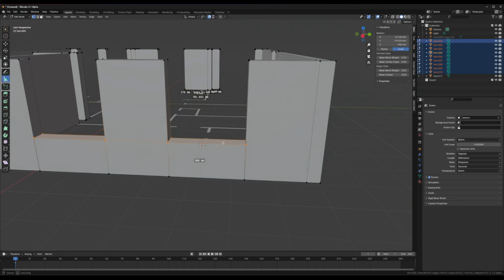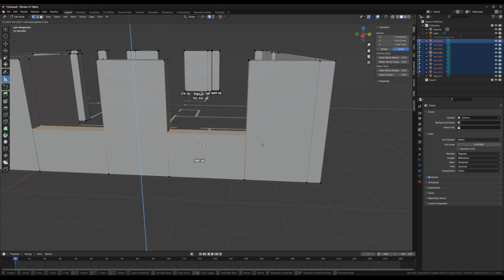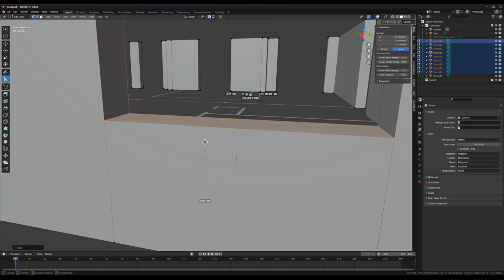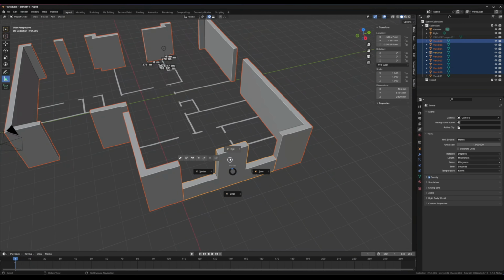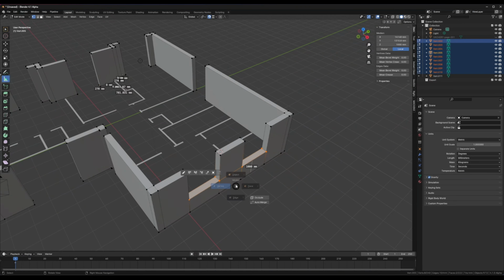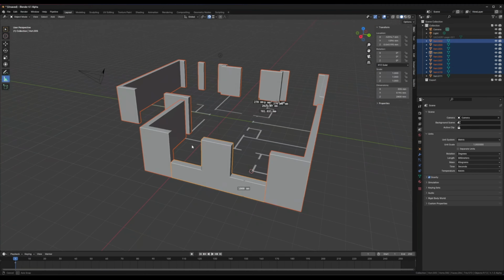And the same if we wanted to move it back up. Let's say we want to move it back up, we just do that, G, Z. So we G Z with all the verts selected, and then just do 100 mils. Now you'll see if we grab this bit, we lock it to the Z axis again, it's up to 1,000. So we're able to move that around, and all these meshes will be separated because we need to have them separated for Lumen in Unreal.